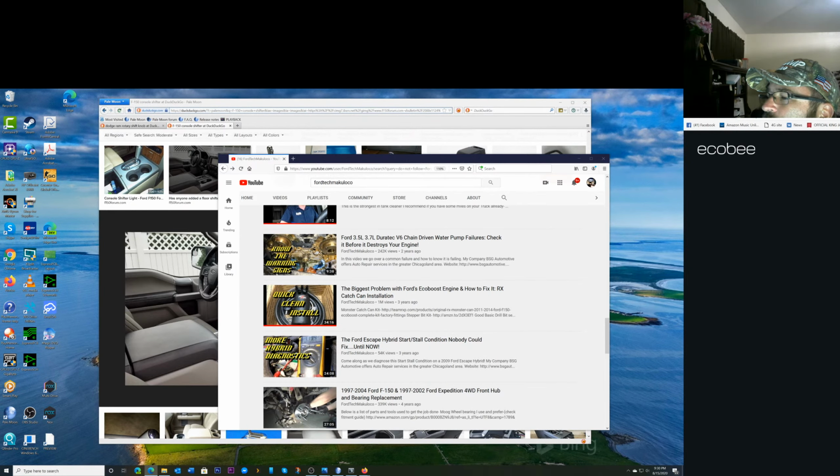But what I was starting to say is that I downsized my unit to a 3-ton for the upstairs, and I totally anticipated it creeping up on the hot days, and then I'd have to put a mini split in one of these rooms and take the room off of the system. But no, I've been able to pretty much get 76. With us coming in and out a lot, loading stuff, I've seen it drift up to 77 twice now, but it would drop back down to 76. I have it set for 75, so it stays a degree above, right? We're switching off the second stage and the first, so it stays 1 degree above until the sun starts going down, then it goes to 75.